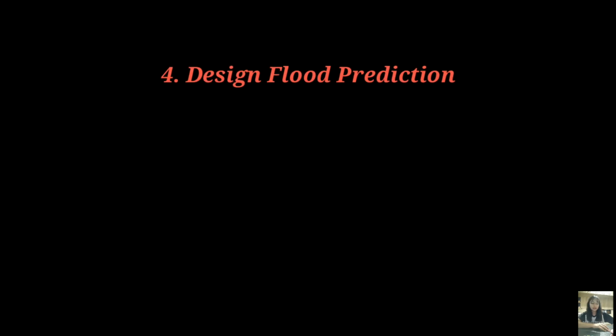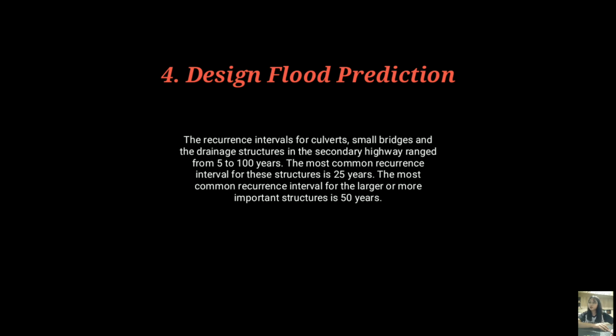And the fourth flood risk calculation procedure is design flood prediction. Unfortunately, so far there is no accurate formulation to calculate the rainfall intensity for precise estimation of flood design discharge. These are approximate formulations, whatever the availability of the data, which lead to approximate evaluation of flood discharge and hazard assessment.